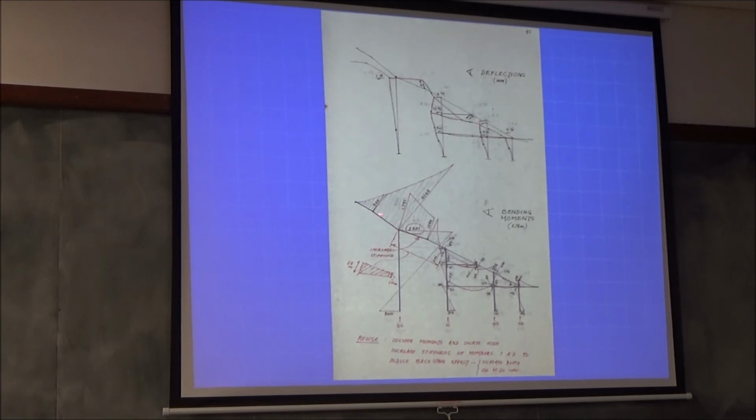So usually when you have a continuous beam, in the back span most of this moment should go here and less should go there. Right? So what will you do to make that happen? First you have to stiffen this part so that the deflection is less. Secondly, you've got to do some trick so that your column moments are reduced. And the beam, because you're anyway designing this part to take this moment, that same steel should be continued and can take the back span. What's a clever trick you can do? That's why you can have a dialogue with the architect and convince him, and then what? Any suggestion?